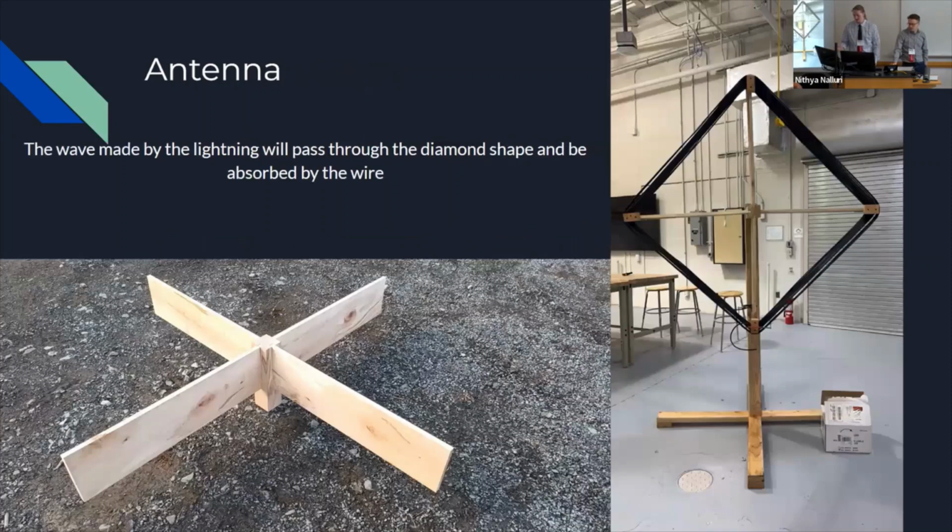So here is the antenna itself. We created a frame loop antenna. It was originally designed as a circle using CADFEKO. And then I took that circle and translated it geometrically into a square, because it's a lot easier to make a square than it is to make a circle. It has a 121 centimeter diameter and it has 30 loops. At that frequency, based off of my CADFEKO analysis, it'll have a self-resonance at around 302 kilohertz. So it's pretty accurate in that regard.